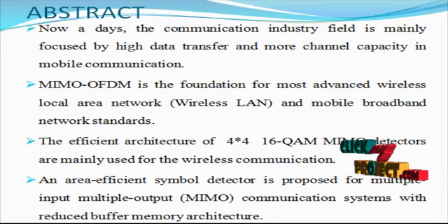The proposed detector starts with an initial estimate of the transmitted signal based on the minimum mean square error detector. Subsequently, it recognizes less reliable symbols for which more candidates in the constellation are proposed to improve the initial estimate.